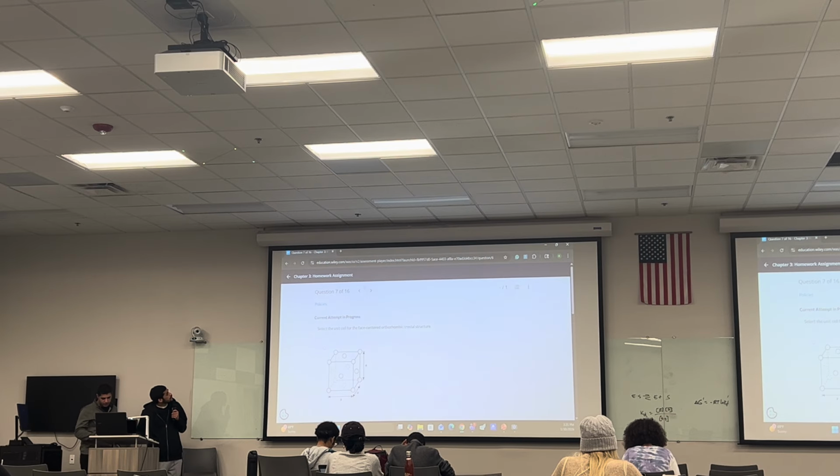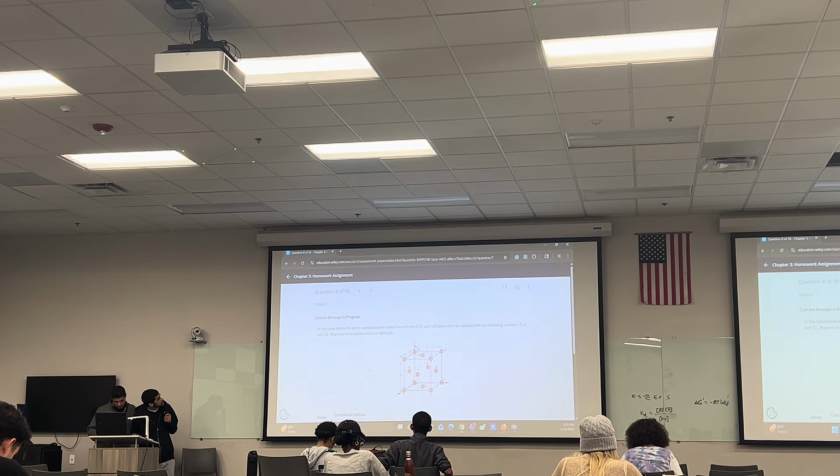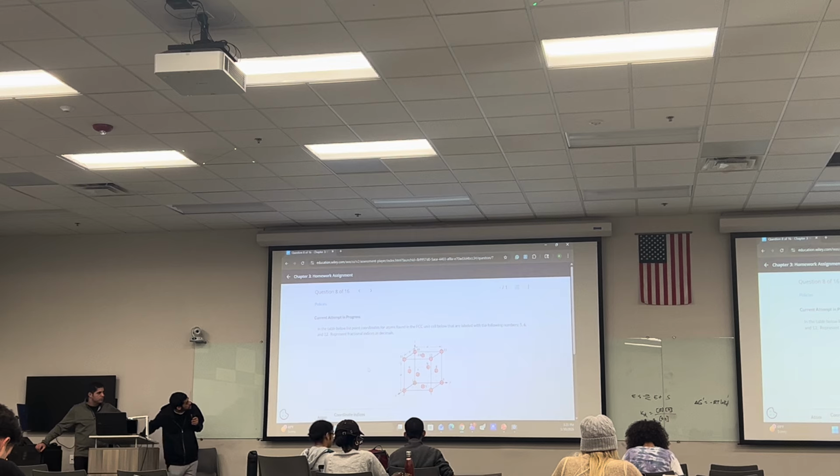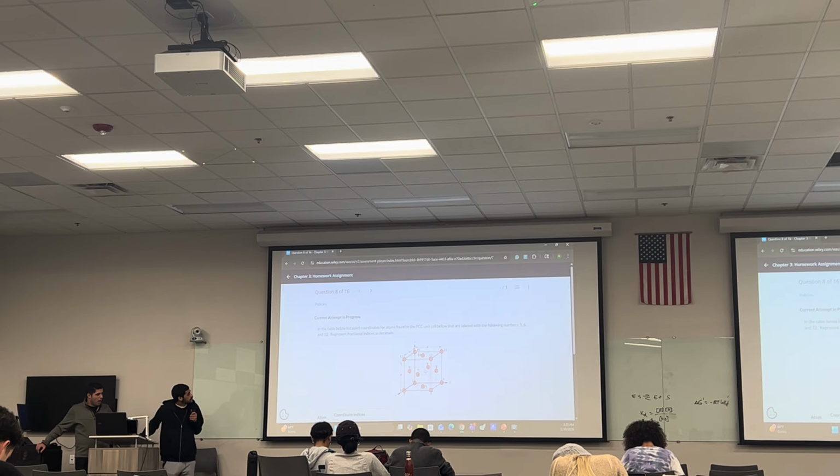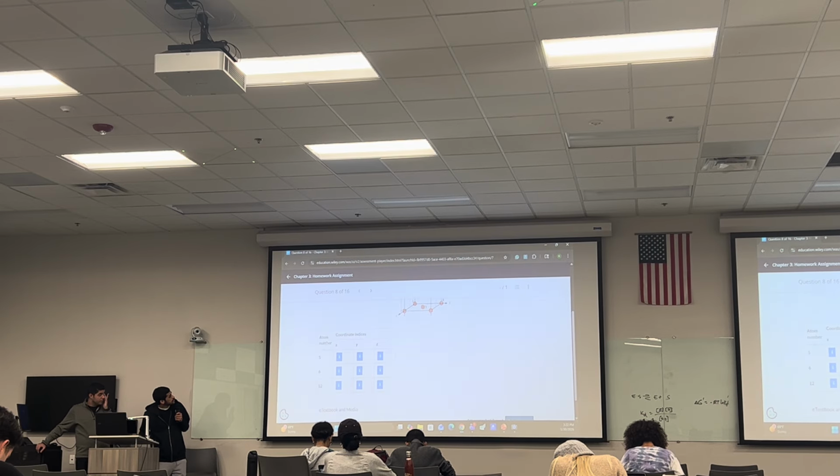So not too bad. For this one, in the table below, they want you to list the point coordinates of the atoms found in the FCC that are labeled with the following numbers, 5, 6, and 12. At least on my side, this guy down here, this guy here, and then 12 is there in the corner. And here they give you the X, Y, Z to actually find it. So we can convert this one.